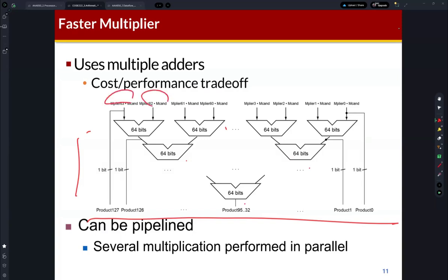So these are partial products, and then many partial products are accumulated by the adders. The results are also accumulated. So using the adder tree, we can implement the fast multiplier, because parallel computation is available for multiplication.